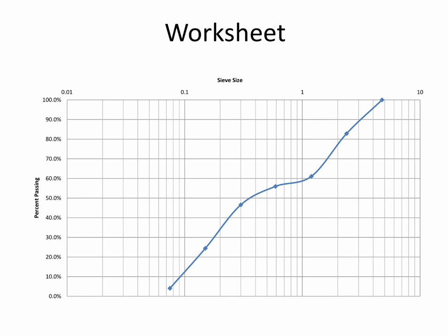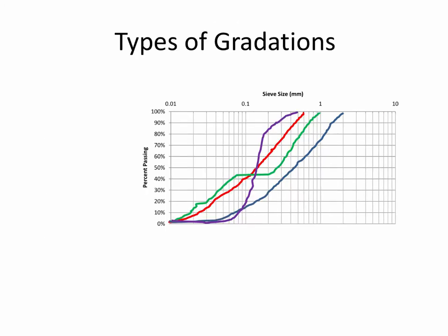And the way that we address our distributions is the final figure that you have on your handout. And here are 4 different distributions that you have. The red distribution is what's considered well or densely graded. So that has pretty much equal amounts of all the different sizes, more or less. Versus the green plot, which is gap graded, up to about 0.08 millimeters, we're pretty evenly distributed.